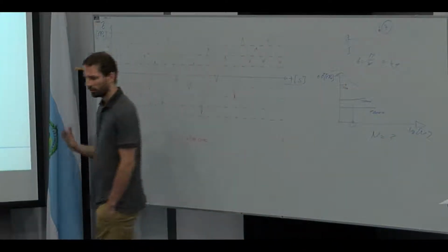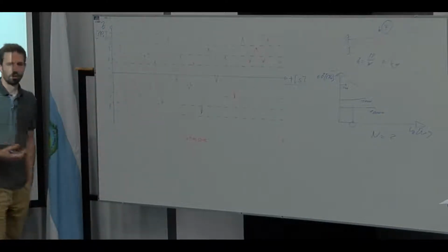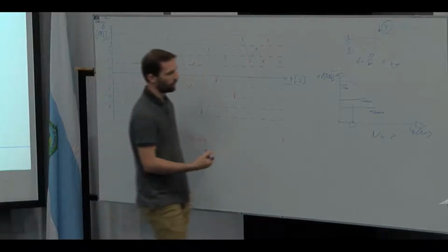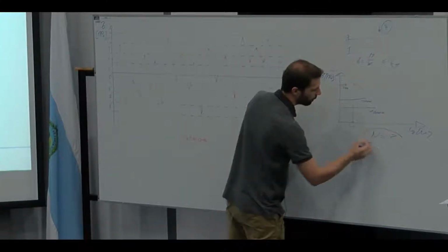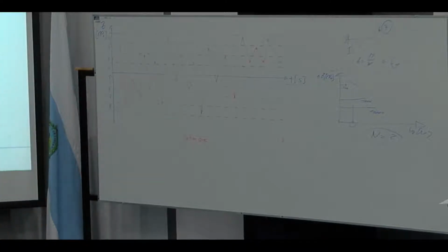So at the end, in your analysis you are just interested in the amount of cycles your structure, your detail, can handle, and therefore you also have to consider other information of your stress time signal to get a reasonable amount of cycles which your detail can take.